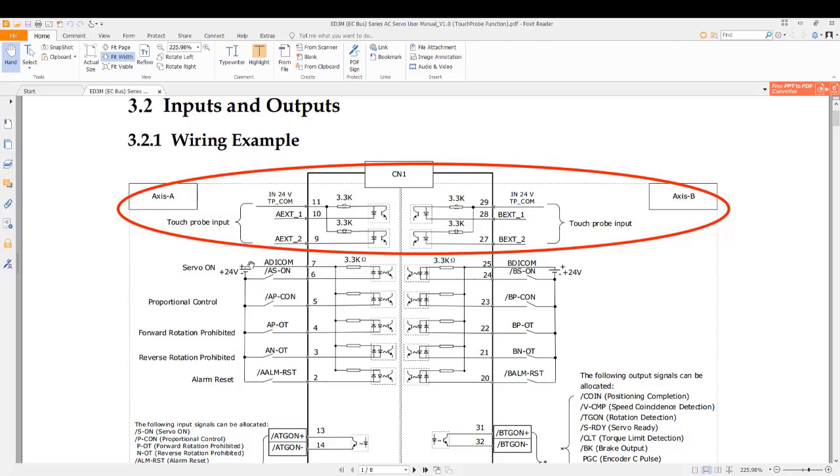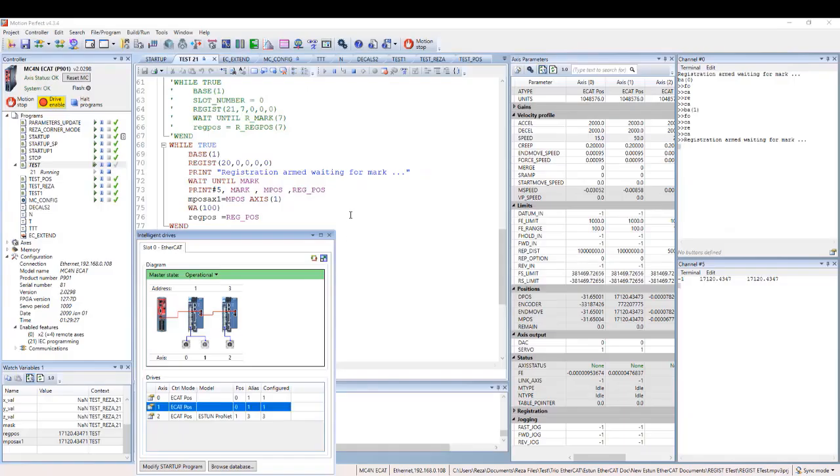In this case, we already wired both digital inputs for both axes, and if we go to the program, here I need to run the second axis, so I type forward running, and the axis is running at high speed, which is 3000 RPM, as we said here, 50 turns per second, which means 3000 per minute.